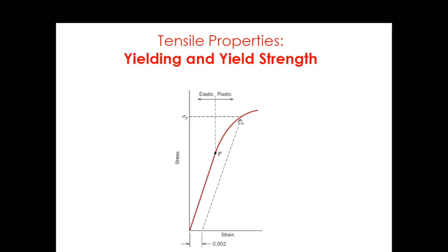Beyond point P, Hooke's law is not obeyed. Ideally speaking, to be very honest with you, there is no difference between point P and the yield point. Both are practically the same. From this point onwards, yielding starts, which means plastic deformation starts. And this point can be very easily identified, the point from which the non-linear portion starts.